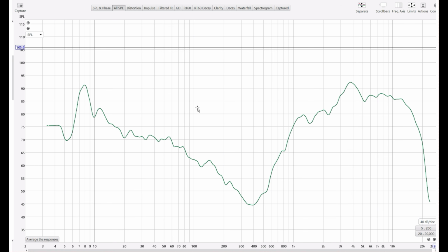But anyway, that aside, when we do a full range measure, we can kind of see where these upper and lower limits are, right? This is where we're asking the tweeter to play higher than it can, and you can see the output just drops off, right? Because you've reached the cone breakup area of that tweeter. It cannot vibrate any faster than that. This particular one drops off at 14,000 hertz or whatever it is, and same on the low end. It gets to a point where it can't play any lower than that because of its excursion limit, right?